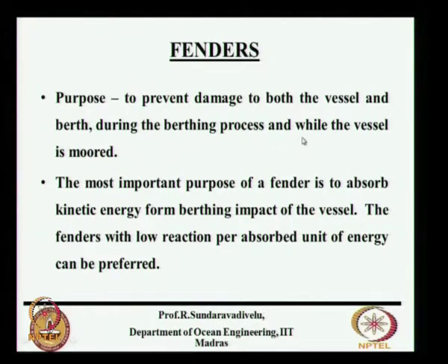When there is a wind blowing towards the vessel, it will be berthing and hitting the structure. When the vessel is pulled away by the wind, then the mooring lines will transfer the load to the bollard. So, when the vessel is berthing, the maximum forces will be there, but when the vessel is moored, due to the operational wind, there will be some berthing force. The damage should be avoided to both the vessel as well as the berth.